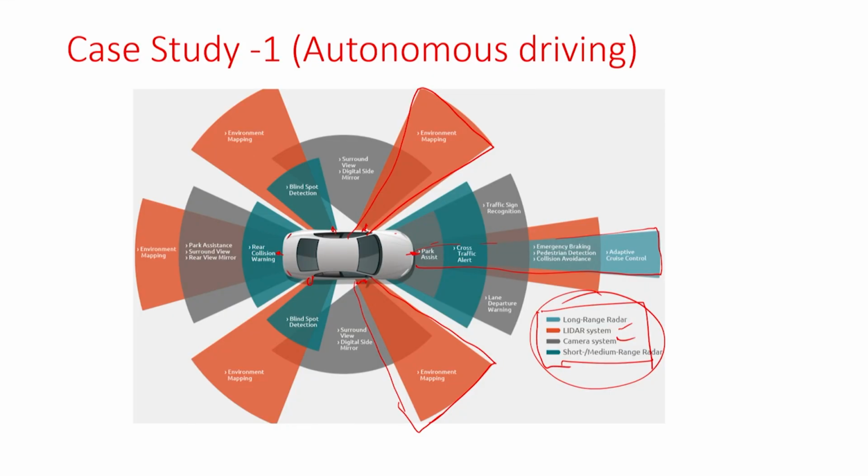Now, the sensors are giving you information. Radar is giving you range, azimuth, Doppler in two dimensions. Elevation is normally not so great, but you get all this information from radar. Camera is giving you information in terms of pixels and x and y coordinates or position. LIDAR is also giving you position plus some amount of velocity as well. With all these three kinds of information coming in, it will be processed somewhere, inside an ECU or some kind of controller. In autonomous driving terms, we call it a domain controller. This controller is just a card.